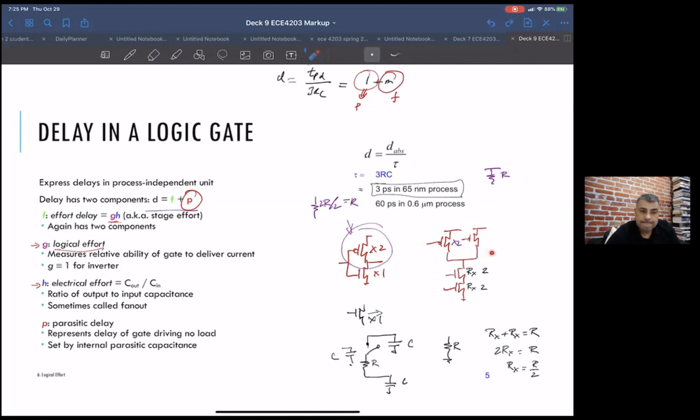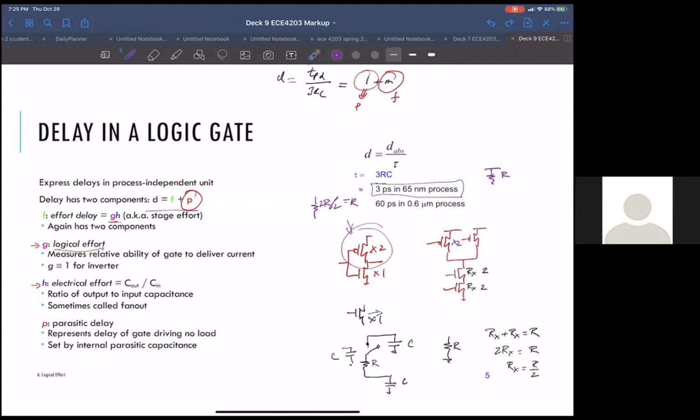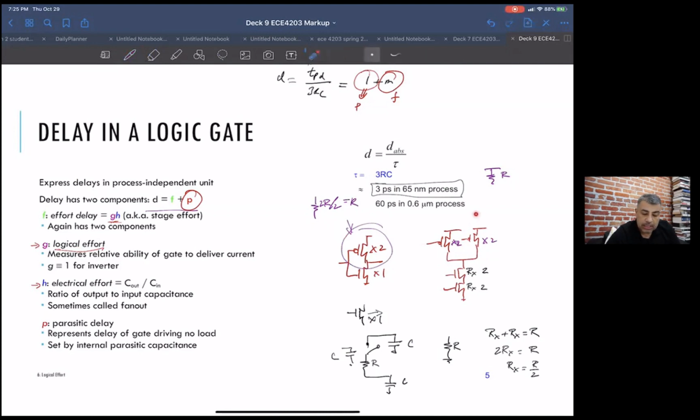Did that make sense? Because you want a sort of a worst case one. So you make this guy times 2 and you make this guy times 2. Now this NAND gate, if you try to get a 0 out of it with these sizes, you make the N MOSFETs twice as wide as these N MOSFET, the pull down resistance is the same as the pull down resistance of our nominal inverter.